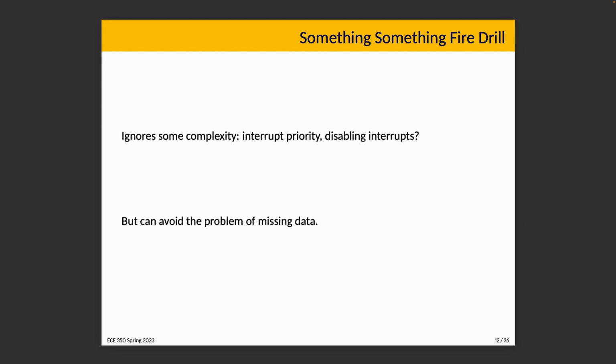The interrupt approach does help us to deal with the problem of not responding in time to the availability of data, rather than making sure that we have to check frequently just in case. Interrupts tell us when there is something to do, but it doesn't mean that an interrupt has to be processed immediately. It might actually be preferable to delay handling it until enough data has arrived. But as long as the data is in memory somewhere, it probably doesn't get overwritten unexpectedly.